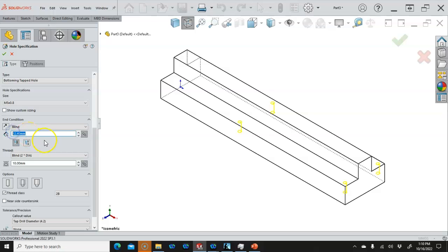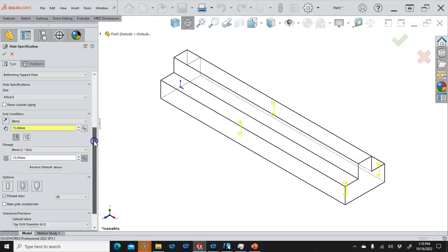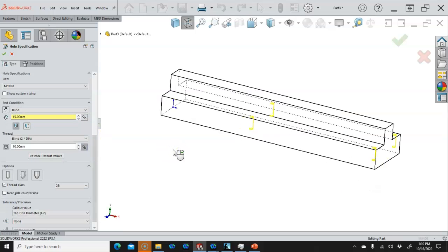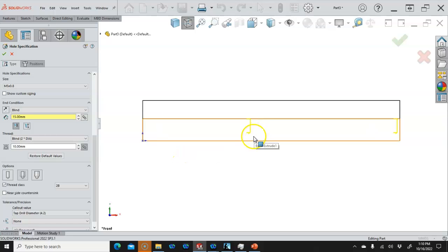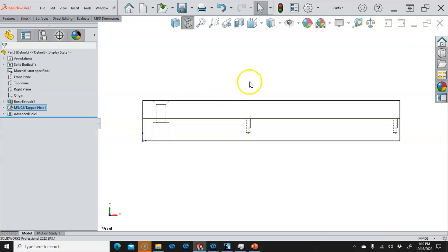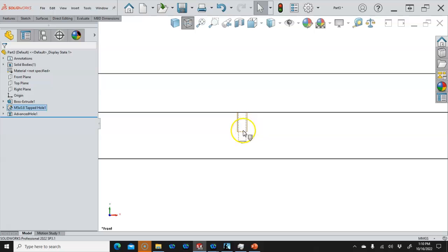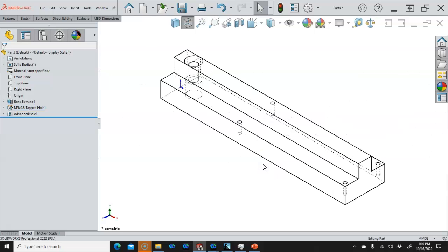So would want to look at making the hole depth 15 millimeters for 10 millimeter. And the 12.4 is close, but as long as I'm not intersecting or going to break through when I don't want to, then it's going to still be good for the geometry. And then we're going to be able to see the cosmetic thread and the hole depth and know that we have plenty of clearance.